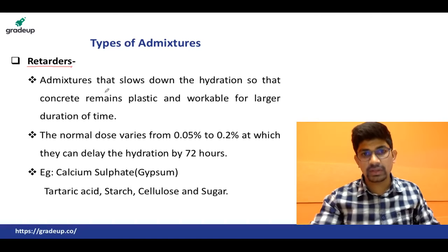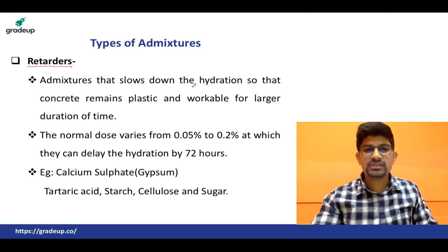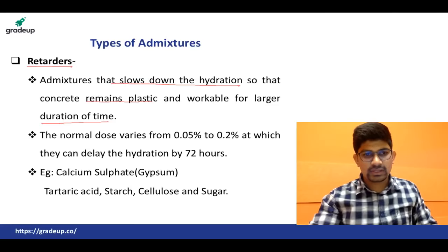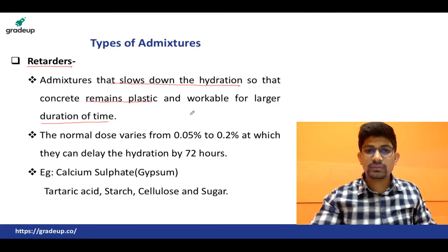It slows down the hydration. Okay, so admixtures that slow down the hydration of cement so that concrete remains plastic and workable for a larger duration of time. So it slows down the setting process. So retarders lead to more prolonged workable concrete.